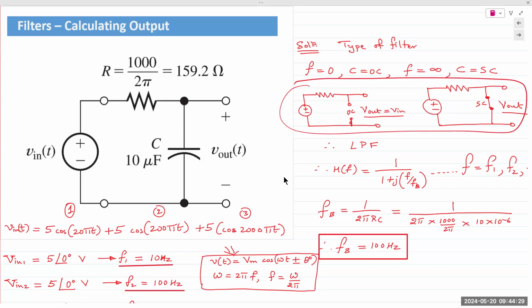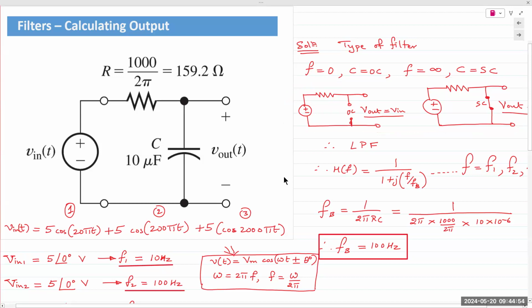And again, as a reminder, the circuit's the same. You have an RC circuit. If you take the output across the capacitor, it's a low pass filter. If you take the output across a resistor, you're obtaining the high pass components. And RL is the exact opposite. So by observation, we know what it is, but if it is a new circuit and we don't know, then we perform our analysis using our table.